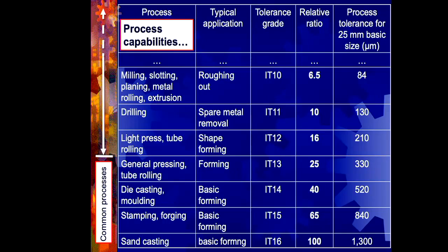We get right down to sand casting. So bells, great big valves. Sand itself is very coarse at that level. You can feel the grain size. So if that is the grain size that the molten metal is pushing up against, then it solidifies. Without subsequent machining, that's the surface effect.